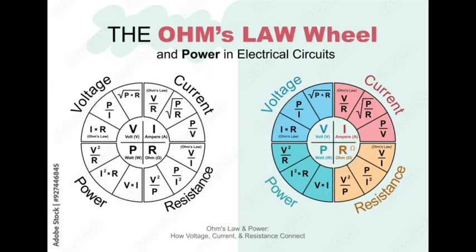A switch, and that switch is gonna turn on 3 lights. Now I'm gonna wire these lights in parallel. So I'm going to go ahead and send my power up to the lights, but before they go up to the light, they're gonna be interrupted right here by this switch. So this wire right here is our power. This wire right here is our white wire, the one that closes our circuit, the one that's called the neutral. And these right here are going to be our lights.